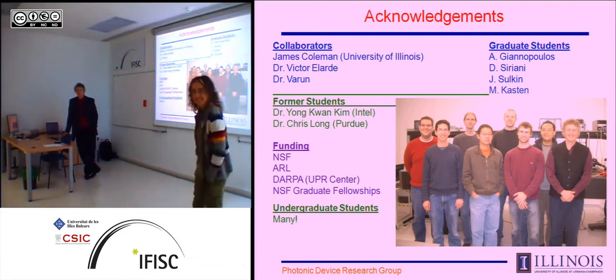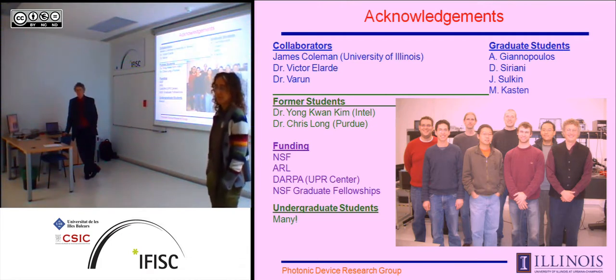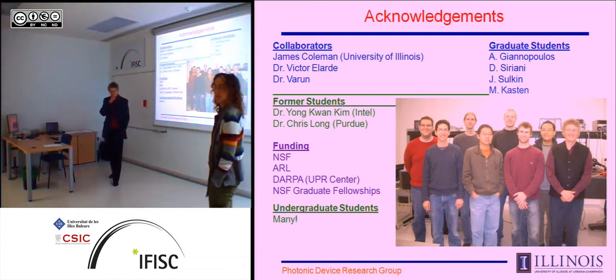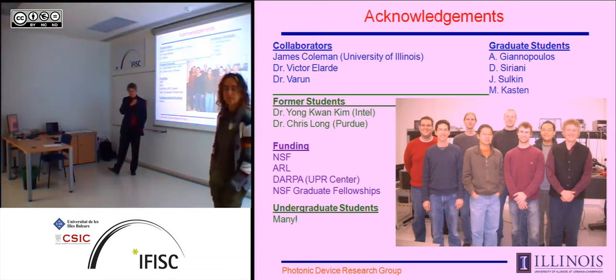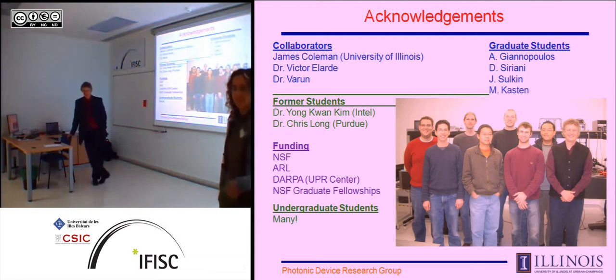Thank you very much. I'm very fascinated by the spatial modulation by the coherently coupled VCSEL arrays. And I think it's not difficult to understand that both the in-phase and out-of-phase solutions can be stable solutions. But you showed that, even under continuous operating conditions, you show this modulation of the angle, which refers to intermediate angles of the locking. Is there an understanding of how far this solution can be stable?